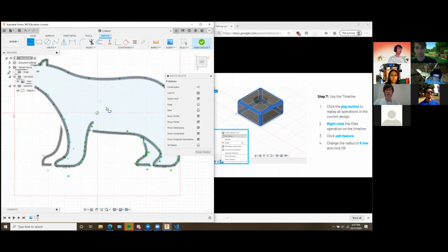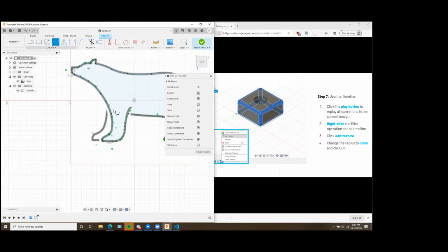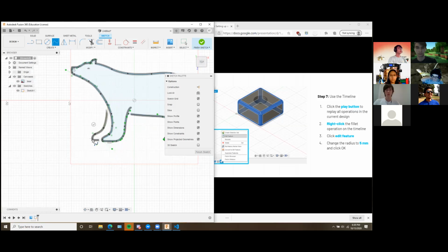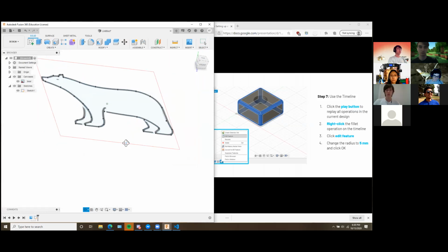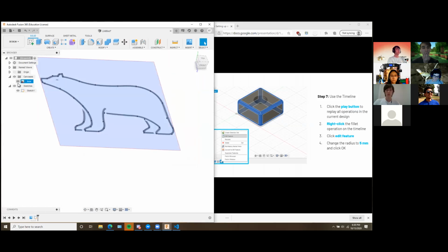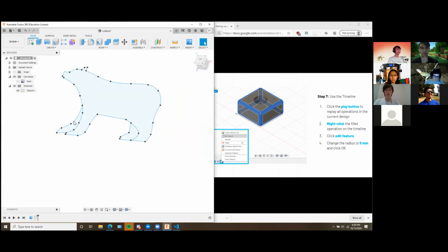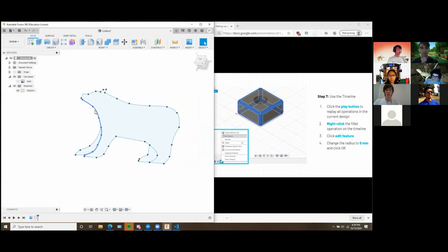Okay, now you see the body is highlighted, and I can do this last leg here. So keep clicking. And then, yeah. So now, once I finish the sketch, I don't really need this image, so I can click the eye icon. And then now I have this bare generic shape. So what you can do is you can extrude, which means to pull out the face. The hotkey is E, but I'm just gonna click up here.